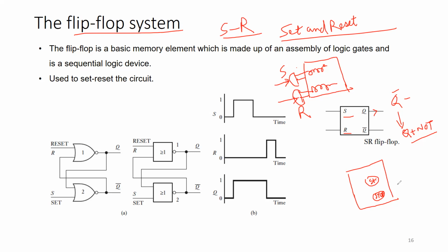Okay, so it has just given a large amount of power for starting, and now it is free. It is giving no response. It has broken the circuit between both, to avoid any power failure or short circuiting. But once a reset button or stop button is pressed, only then will this spring operated switch come back and the start button will be activated.